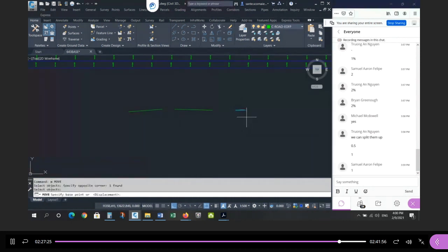And I want to put that in here. I want to splice it in here, right? So then I go from positive 1.5 to positive 0.5, grade change of 1%, positive 0.5 to negative 0.5, 1% grade change. So this is what I'm going to do. I'm going to move this line so that it ends here, and I'm going to move this line so that it starts here. And that's what the profile needs to look like.